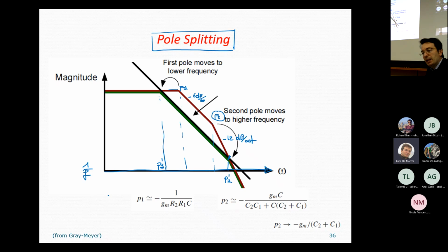So if this is the VSD of transistor 3, this is the VSD of transistor 4, this is transistor 6, 7, and so on, 5, 1, and 2. So we want VSD of transistor 3 to be equal to the VSD of transistor 4.